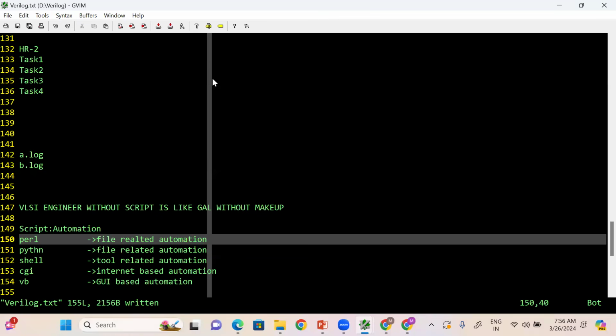Okay, we'll do one thing. I have given all the languages' introduction. Now my work will be to deep dive into Verilog. From tomorrow, what is your data type? What are continuous assignments? What are procedural assignments? In always blocks also you have different types: always latch, always flip-flop, always combo. What is the difference between monitor, display and so on? A lot of things, so all that will go one by one.